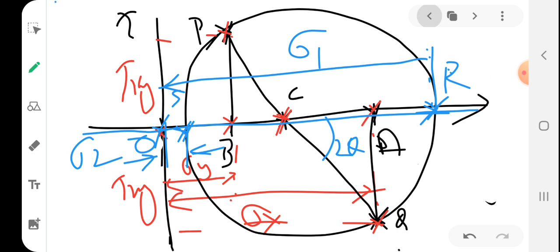So students, if this angle is some 60 degree, then the angle of principal plane from the current state of stress is half of 60, that is 30 degree. You will understand things when you do problems. Okay, so we will do problems in the coming session. So this is how you find principal stress or principal strain, principal stress and principal plane.